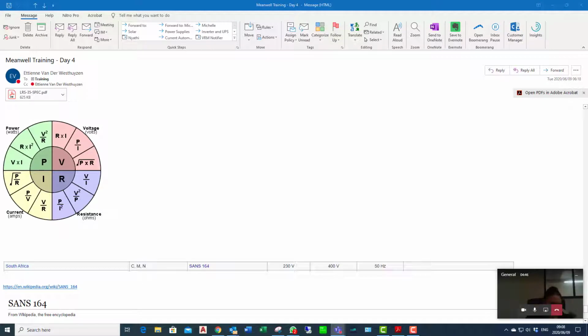Okay, so we've got 35 watts divided by 240. So we're looking at 0.165 of an amp. So if you've got an ICL 28, right? An ICL 28 can supply you 28 amps. So 28 amps divided by 0.1657 will give you 168 power supplies. So the answer is not 6, Natasha. You're on silent.